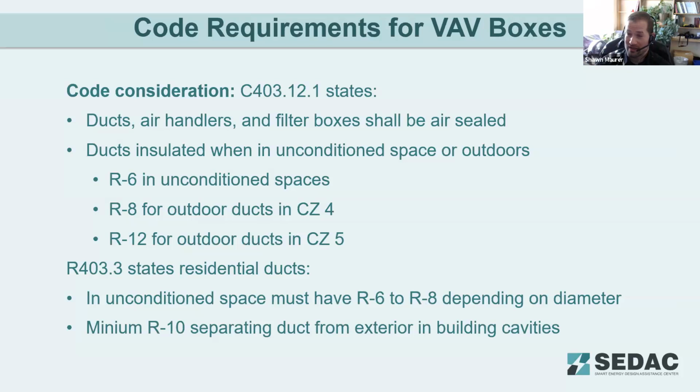For the energy code compliance, again, insulation is required by the code in unconditioned spaces and on outdoor ducts. That's when this is now mandated by code. A lot of times this insulation is in place for noise control purposes and not actual insulation needs if you're installing this on an interior plenum.